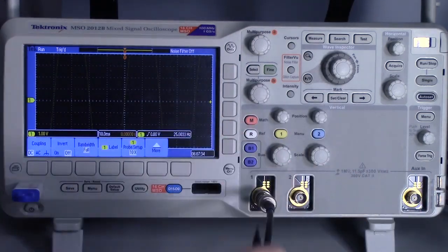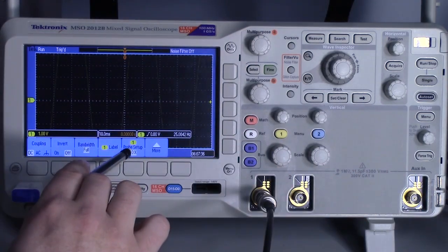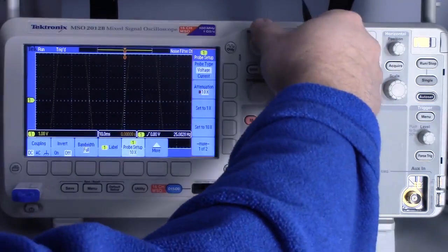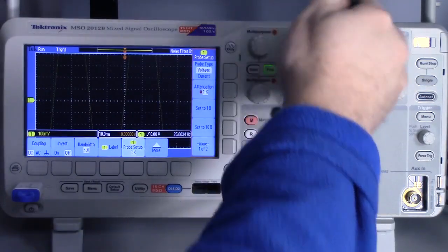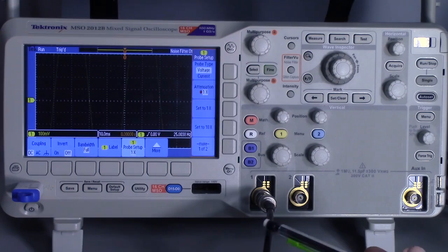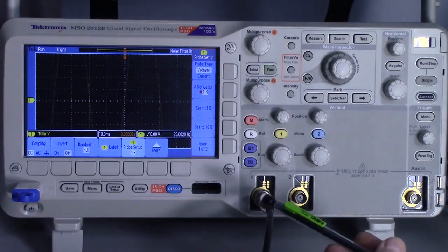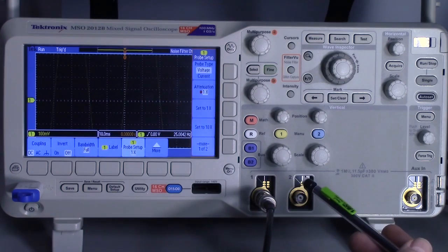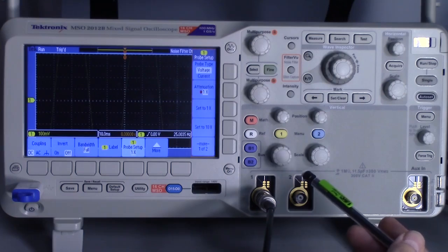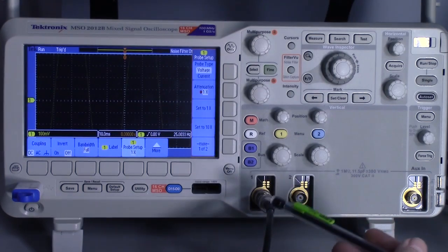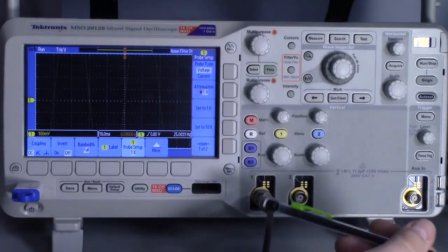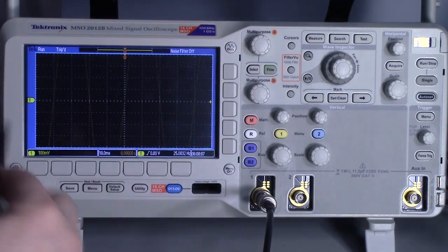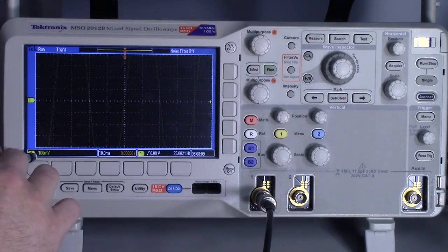So I want to change, this is just a coax cable. I don't want this probe setup to be 10x. I actually want to change that to 1x. You would use the 10x if we were using the 10x probe. The 10x, I'll get into this in another video, has to do with the attenuation. It has to do much more with the scope probe and the bandwidth of the scope probe. But for this, since this is just a coax cable with a terminator, I want 1x.